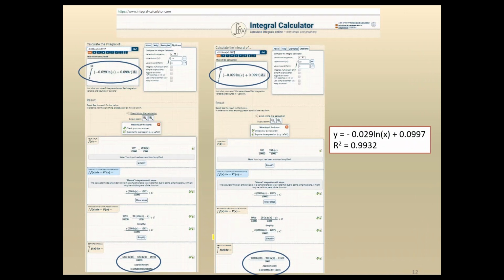So with that equation that was generated, we then go to an online integrator, and we happen to use this one that seems to do a good job and is fairly straightforward. The equation is inserted here, and then we conduct the integration from, what I typically do is 2 to 15 feet, and on the right-hand side I do one from 2 to 20, depending on what one thinks is the appropriate depth of the zone of moisture change.